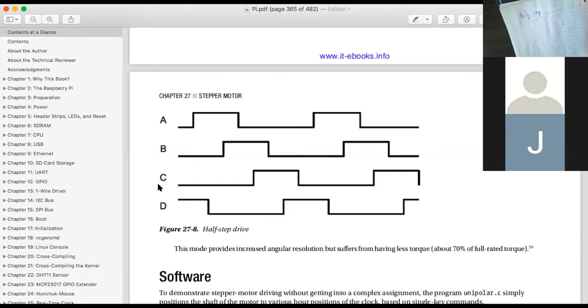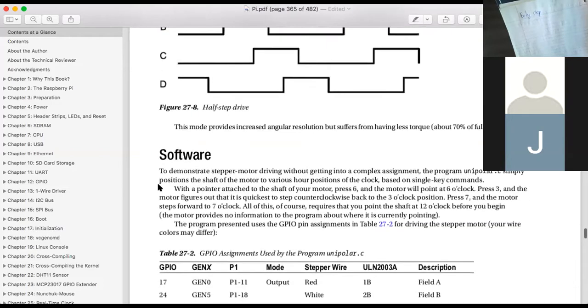So baby stepping is another way. We can control the stepper motor in greater detail. Instead of 7 degrees, we can rotate 1/4 or 1/8 of a full step, or 1/16th, or 1/128th of the steps forward or backward, if we do have that kind of requirement. So baby stepping.